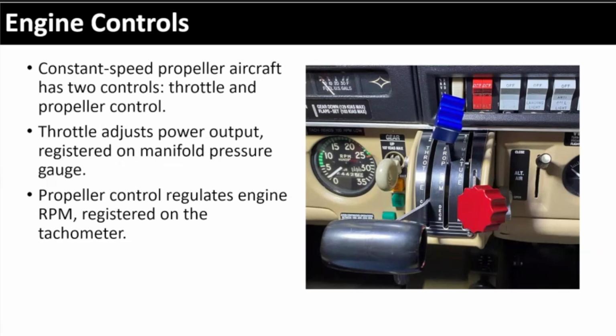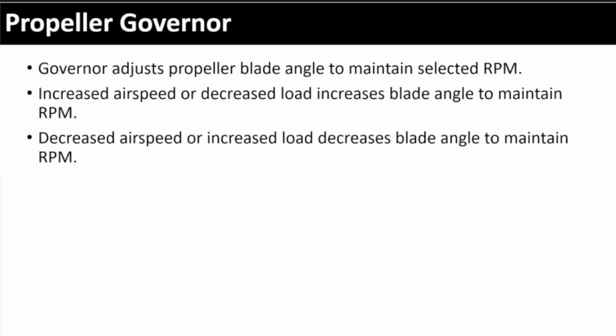You can adjust the throttle and add more power. That's not going to increase the RPMs. You will get more power out of the airplane, but you're not going to increase the RPMs. Okay. So the RPM gauge is really indicative and mapped to the constant speed propeller. That's correct. That's right. Yep. Okay, all right.